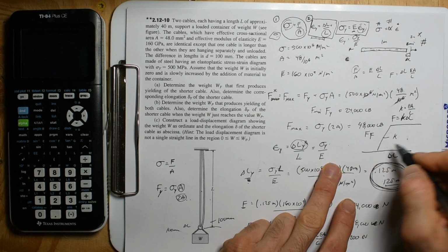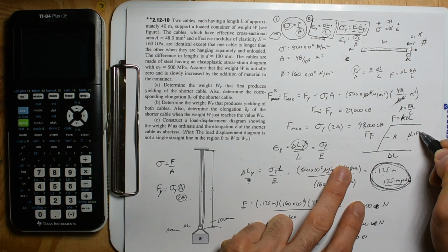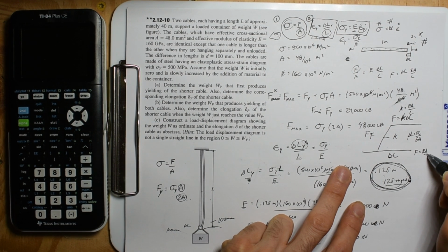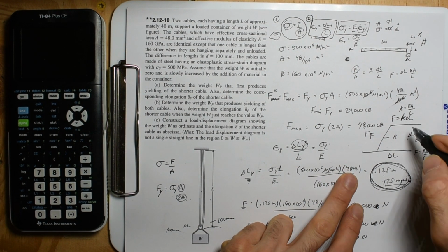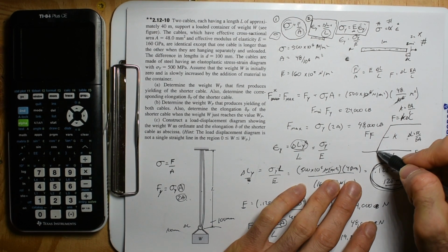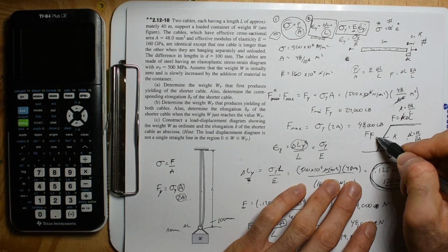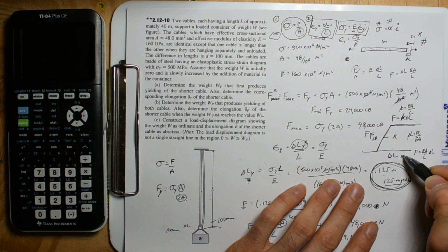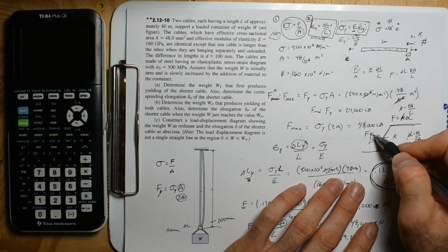And then we know that change in length is FL over EA, and then you can rearrange, get force on one side. Force is EA divided by L, change in length. So just being able to do that real fast is very helpful. At the end of the day, I know how many pounds I'm going to put on something, and then I can measure the change in length in inches, maybe with calipers.